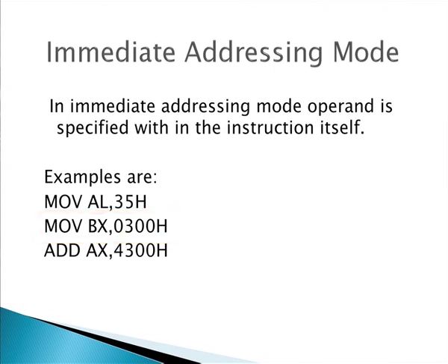Similarly, we can have more instructions like ADD AX, 4300H. Here the contents of the AX register will be added with immediate data 4300H and the result will be stored as the contents of AX. Again, the addressing mode is immediate as the operand is defined within the instruction.